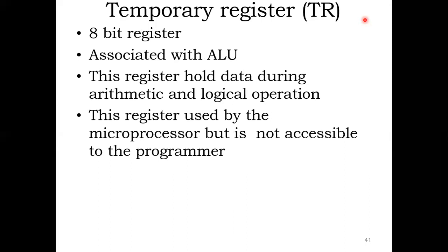The temporary register is an 8-bit register associated with the ALU. This register holds data during arithmetic and logical operation. This register is used by the microprocessor but is not accessible by the programmer.